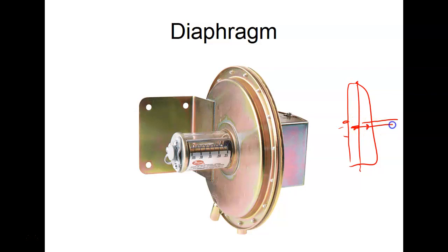This brings a rod out the back, and then whatever we're going to transfer it over to, we take a linear motion and convert it over to a voltage, or it's attached to the rod. A very simple sensor. But this is just the sensing element, right, that we're passing around. We have to take the sensing element and run it through another transducer to take a displacement and convert it into an electrical signal, right?